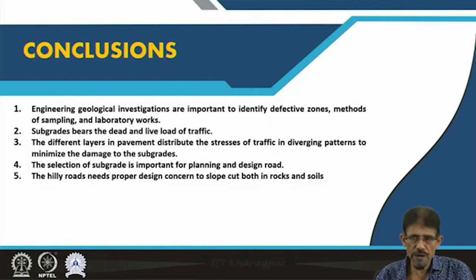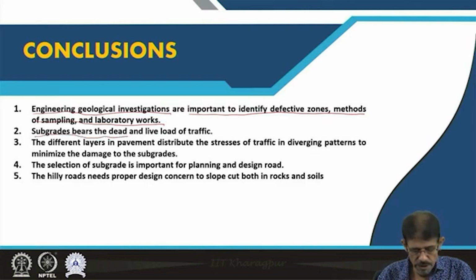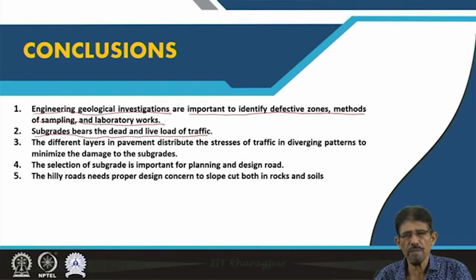Friends, in this lecture we have elaborated about the engineering geological investigations or facets required to identify defective zones, methods of sampling and laboratory methods, as well as for assessment of level of treatment, preparation and cost involved in preparation and treatment. The subgrade bears the dead and live load of traffic. Therefore, we are going to make different layers above the subgrade to distribute load in a wider area, so the minimum deterioration effect can be experienced by this subgrade.